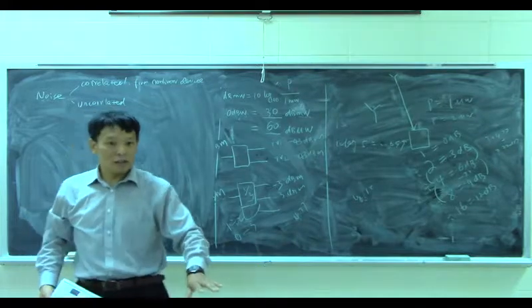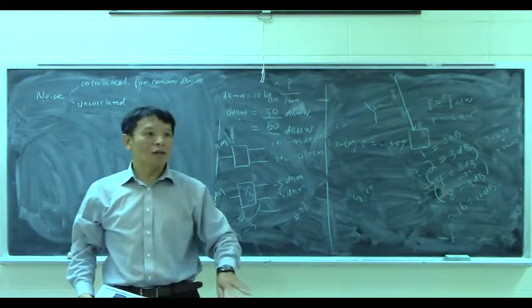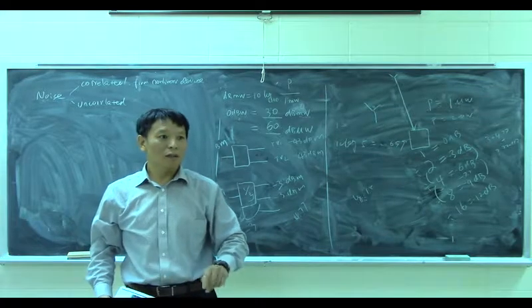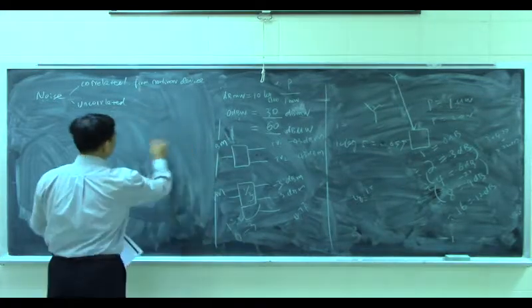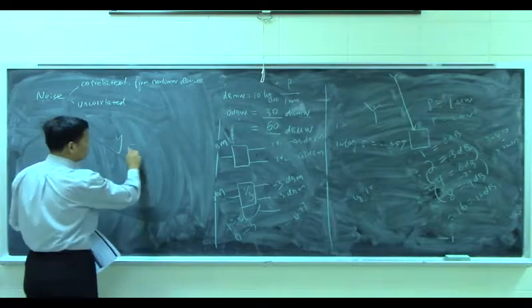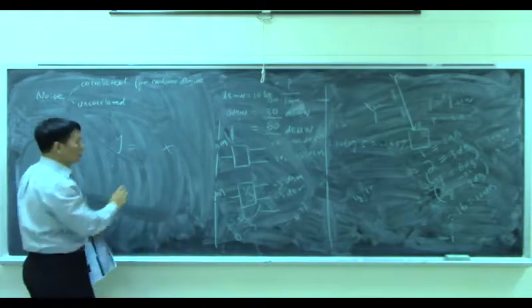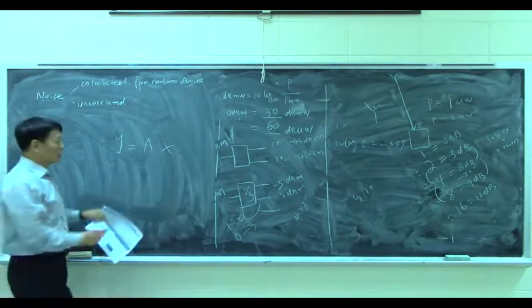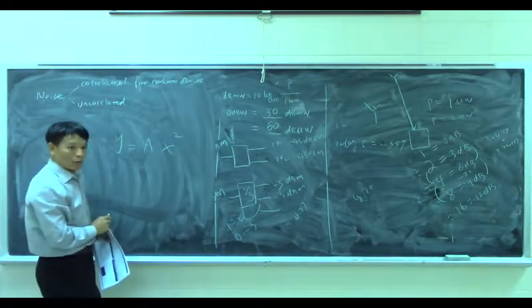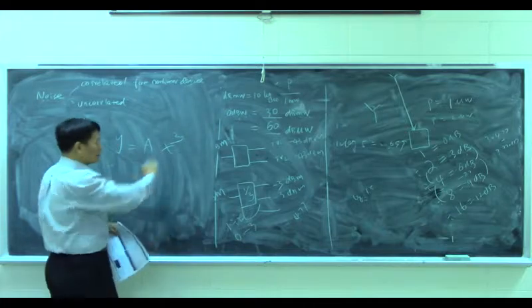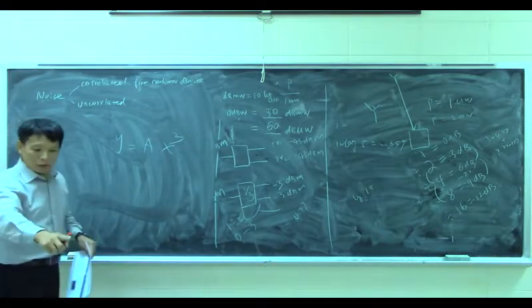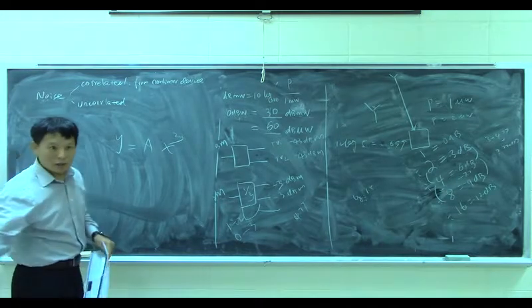There are transistors inside. We know transistors are not a linear device. It is nonlinear. That means the output related to the input is not just multiplied by a constant. This is a linear circuit, right? Instead, it will be squared, even cubed, even higher.